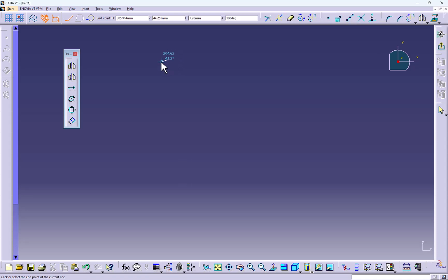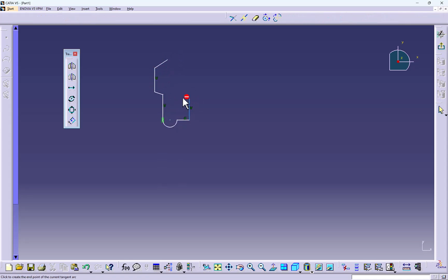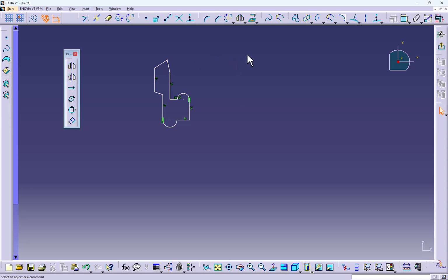If I create something to be mirrored, for example, any random thing is getting created. Okay, like this, I created one part. Let me make one axis as our mirror line. Okay, I need a reverse image of this portion on this side. So first we'll select that object to be mirrored, and then we'll go to the mirror tool, either from here or from here. We'll select the center line, and we can see we got a symmetrical object. That's called mirror. Now let me undo.